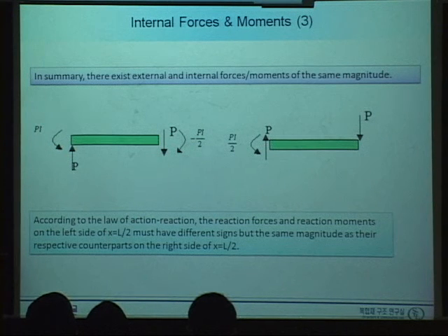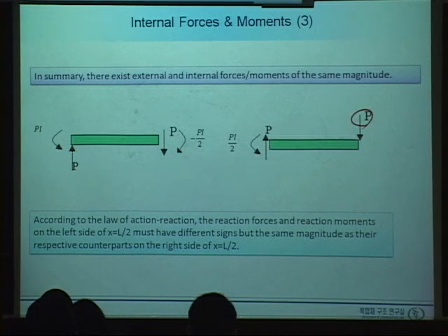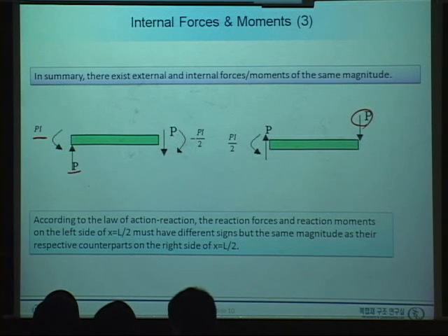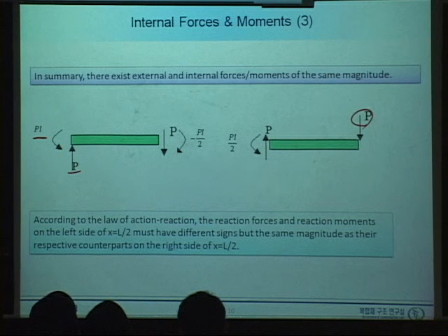So if we summarize the internal force, when this whole beam is subject to a P at the end, the left-hand side is clamped, and the reaction force, bending moment, and shear force are calculated from whole equilibrium.